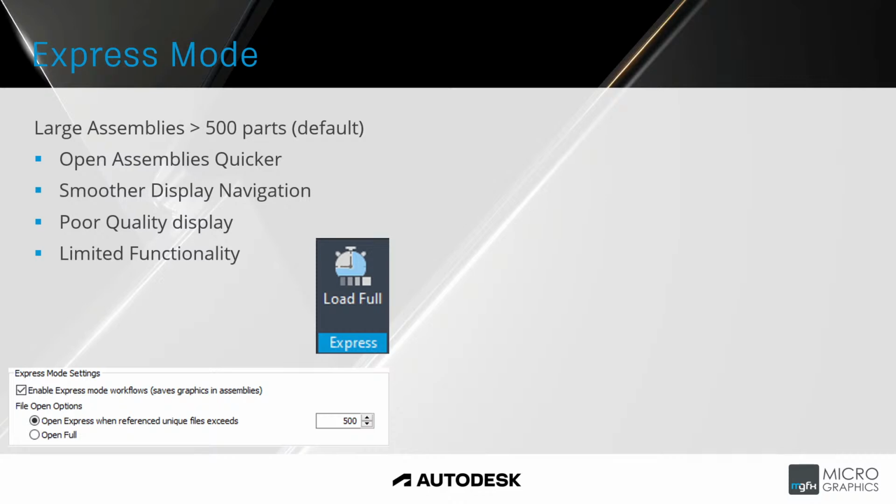So starting off here with Express mode, what Express mode does is it loads a limited assembly, limited graphics and functionality assembly. By default, Inventor is set to load in Express mode if your assembly has more than 500 parts.